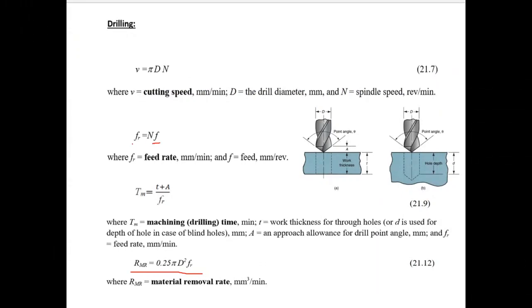The feed rate for both of the drill bits is the same, which is this much. However, the feed could be different and it is a function of the spindle speed. And it was mentioned in the statement of the problem that spindle speed could be set individually. So what we need to do is to compute the spindle speed for each of the spindles first.